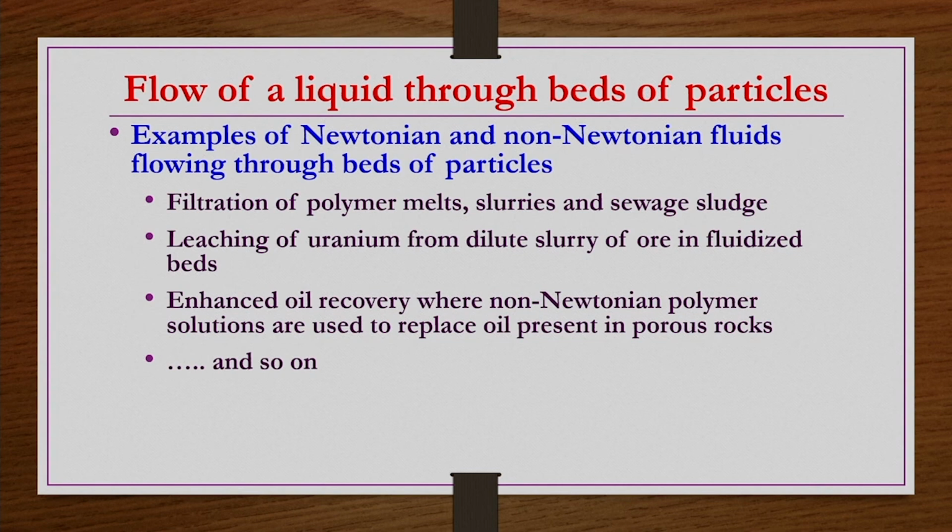Having these many applications, obviously it becomes essential to find the pressure drop, because wherever there is a flow, it is essential to have a relation between volumetric flow rate and pressure drop, or equations for the pressure drop or friction pressure drop calculations. That is what we have been doing for so many geometries, because pressure drop comes into the picture in velocity distribution, volumetric flow rate, etc. So indirectly we have relations. If you have the velocity, you can get the other quantities. If you have a known fixed volumetric flow rate, we can calculate how much pressure drop you need to apply.